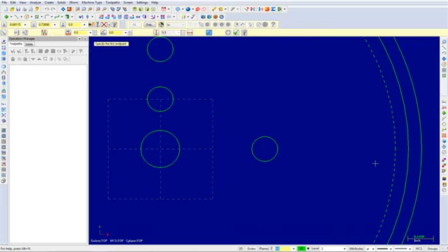Now select the following arc as shown. Make sure that you are not selecting any endpoints, midpoints, or quadrants from the arc. If you select one of these points, Mastercam snaps to the points and disregards the tangent option. From the ribbon bar, enter a length of 1.5 at an angle of 20 degrees. Press enter. You can now choose the Apply button to continue making lines.